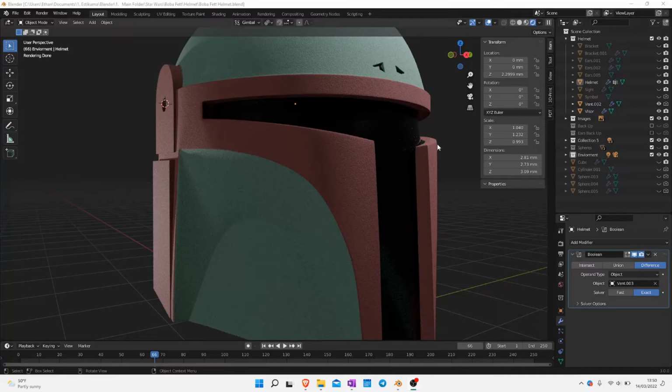And what I did originally was that I designed this front part with just planes, so that I got the shape of the helmet like it is here, and then I used the Solidify modifier to add on 5, 7, 8 or 10 mil of thickness to it, so that it would be strong enough to be printed. And that's essentially what you would use the Solidify modifier for, to input thickness onto your props, so that when you're printing, you'll have walls and it'll be strong. If you're using it for animation, it's good for 3D walls for games or other things like that.